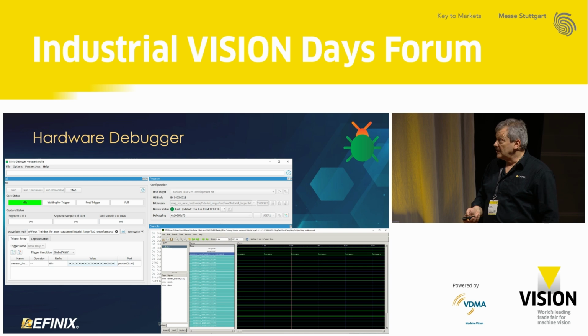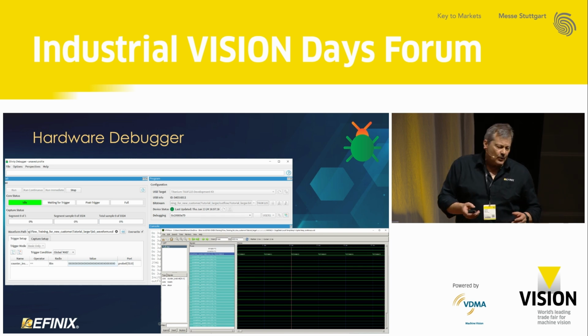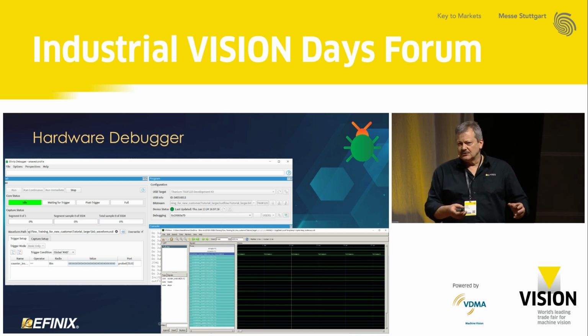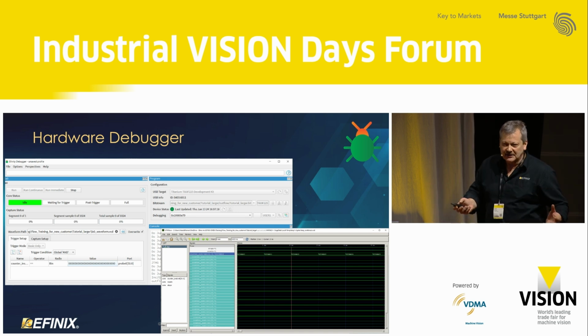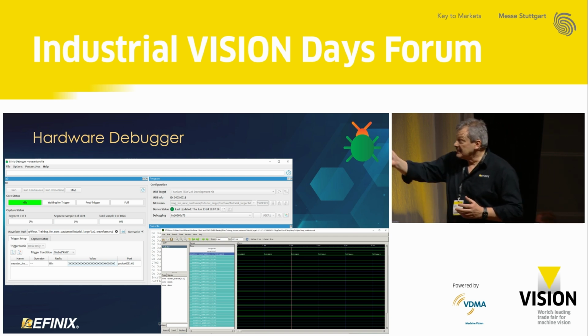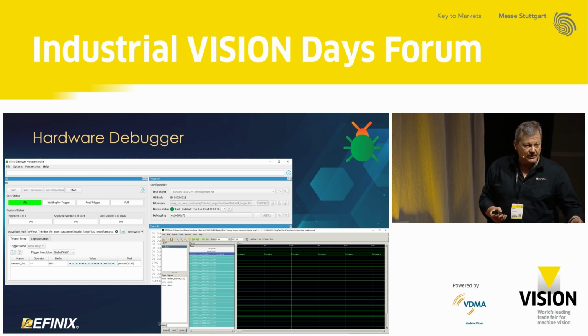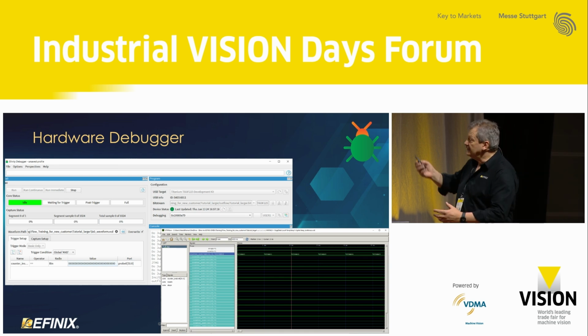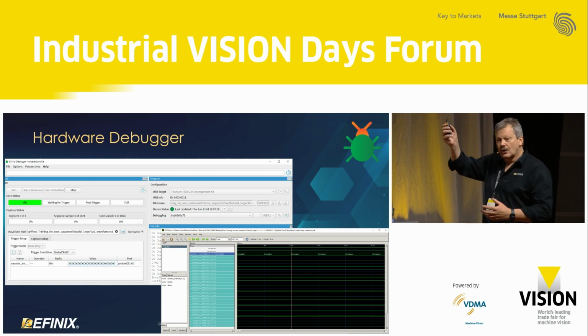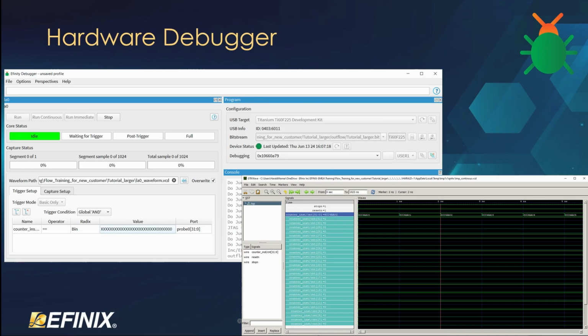Package view as usual and a hardware debugger. So we do not have these fancy names like all the others. We are just calling it a debugger. You can automatically instantiate this debugger in your design. You can add some trigger points to some signals. If the trigger point is reached, then we generate a VCD file, and you can see all the internal signals from your design.